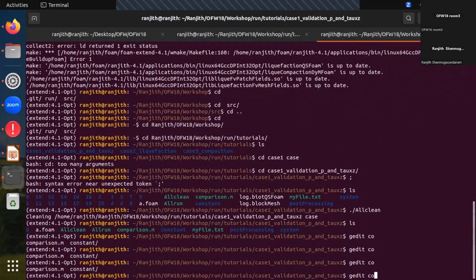So we need to create a block mesh for the seabed, and in that the length of the seabed will be equal to the wavelength, and the height of the seabed would be the domain's height.